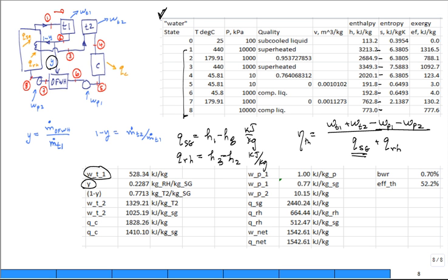And the same per kilogram scale is the kilogram that goes into the first turbine stage. That's the notation in the textbook, so I'll try to stay with that notation. So this kilogram is what went to reheat. But if I multiply by kilogram reheat divided by kilogram first turbine stage, those kilograms cancel, and I've modified it.